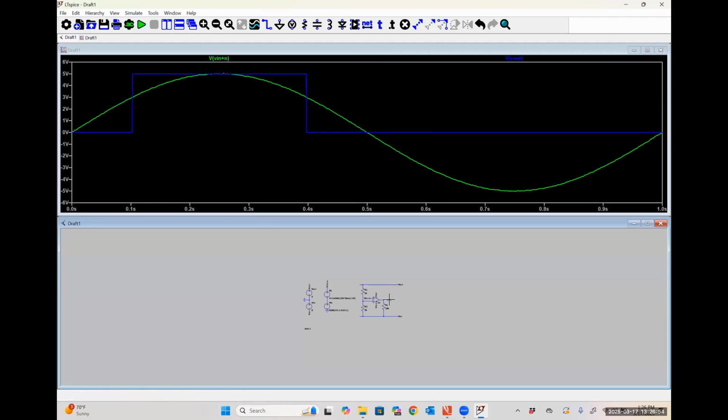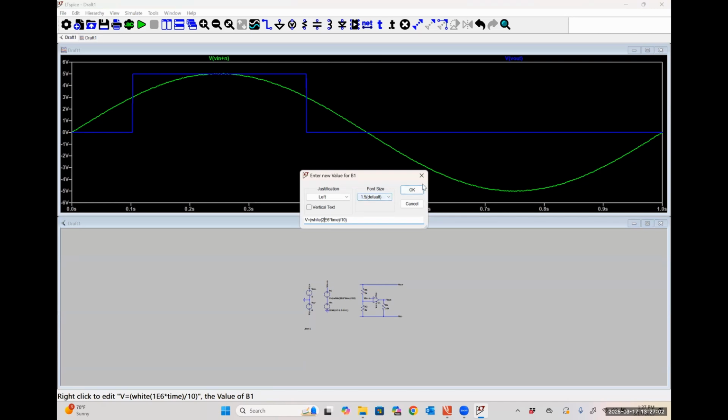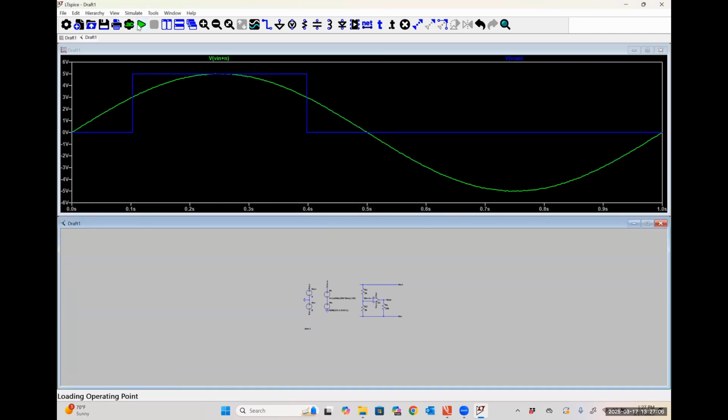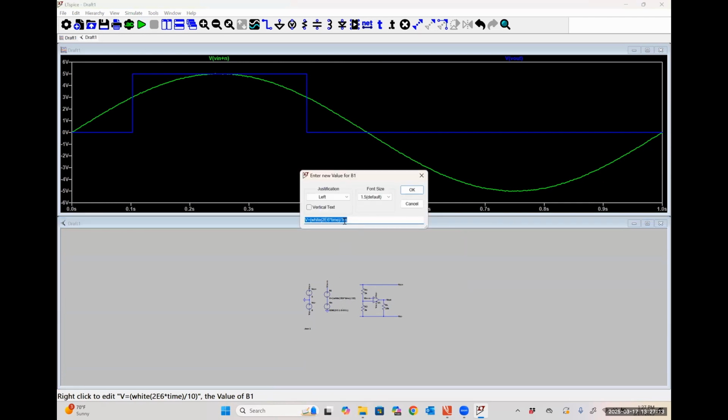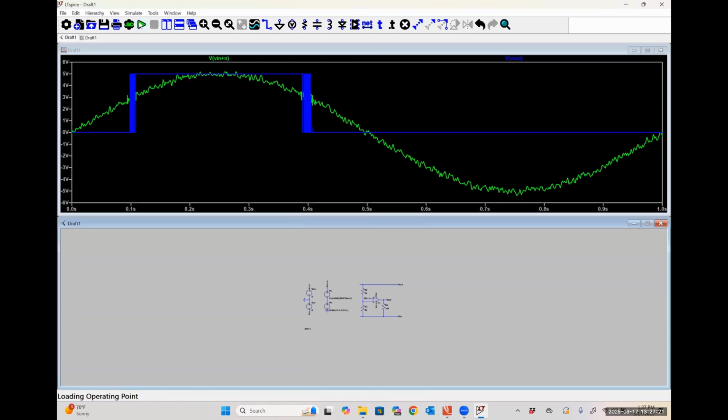Well, when I look at my output voltage, that's not as gross as I want it to be. There we go. Now it's real gross. Okay. So the size of that noise ripple is only on the order of probably 100 millivolts, right? What's going on in this region right here and this region over here? Is it dropping really fast between 0 and 5 volts multiple times?